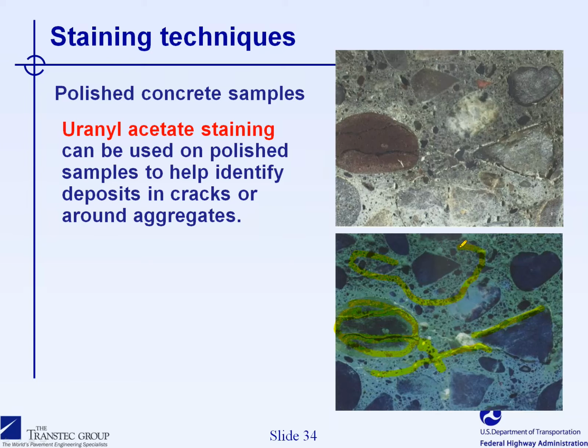So in general, I would say that not all the voids you can see here will be filled with the gel, because most of the time what you see is gel being found along the cracks, as you can see in this slide. But you will not necessarily have gel oozing out of the reactive particle to fill the paste around, not at least to a very large extent. The gel is very much concentrated in the cracks.